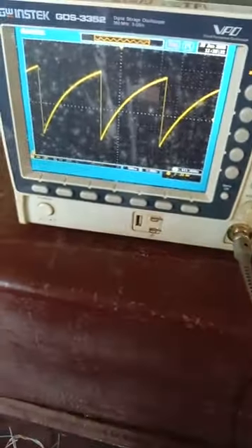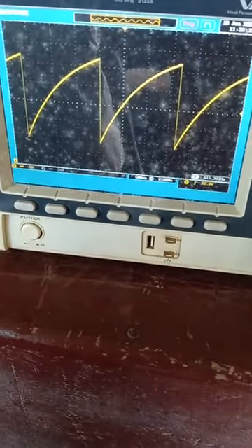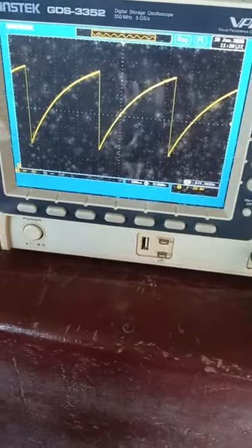Reduce the power supply to 0. Reverse the polarity of the power supply connected to your circuit. Put the power supply at 40 volts again. Is the polarity of the sawtooth inverted? Let's see the waveform very well now. We are going to interchange the terminals and see how the waveform will look. I hope you are following. Let's go and see now.